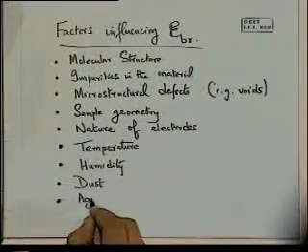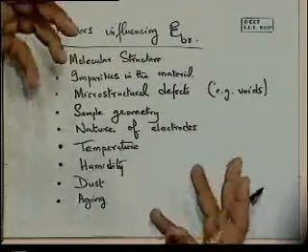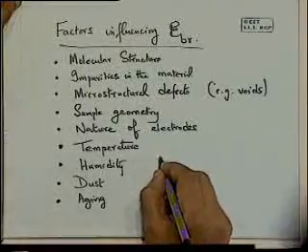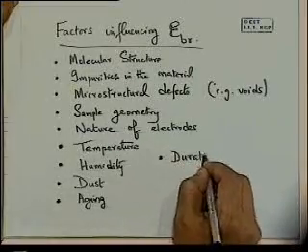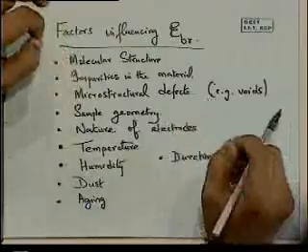Aging. The material itself is deteriorating with time. Its properties are changing, and gradually, as it grows older, we may say the bones are getting weaker, the teeth are falling out. That's what happens in human beings. Dielectrics also age. And then it will also depend to some extent on the duration of the applied field. How long did it endure a particular field?